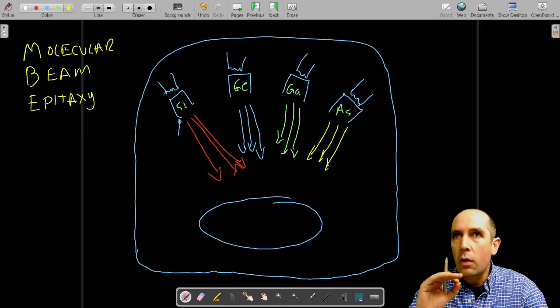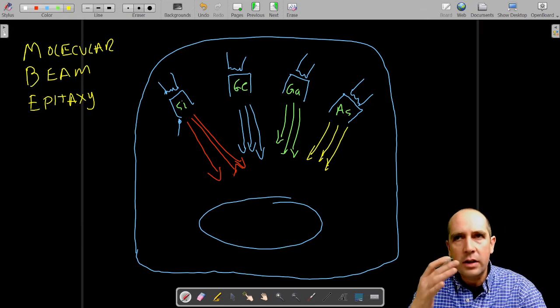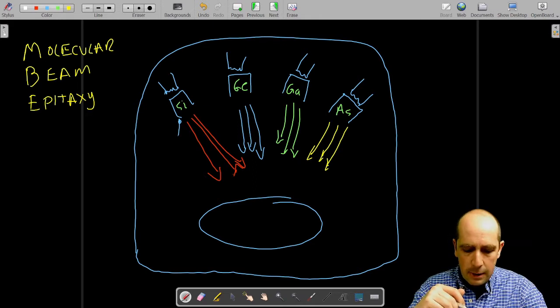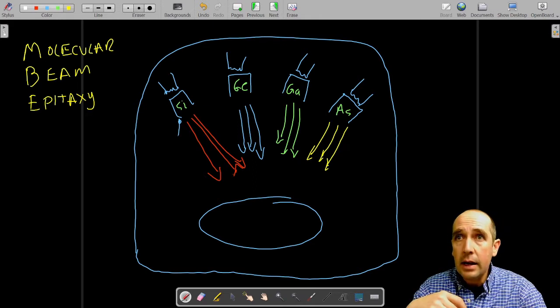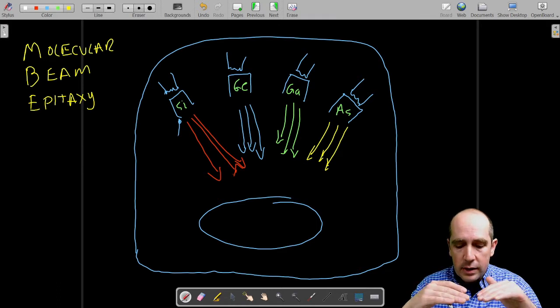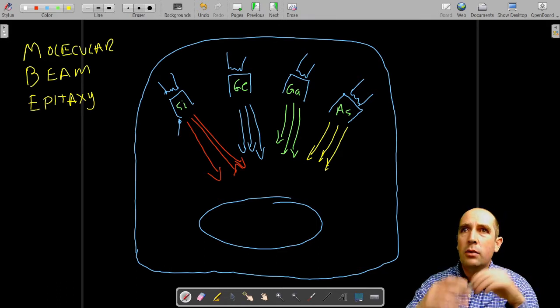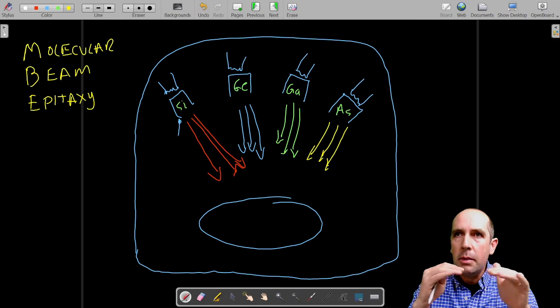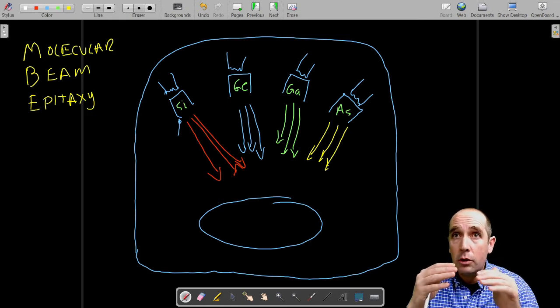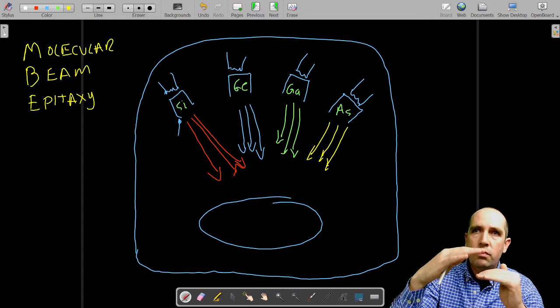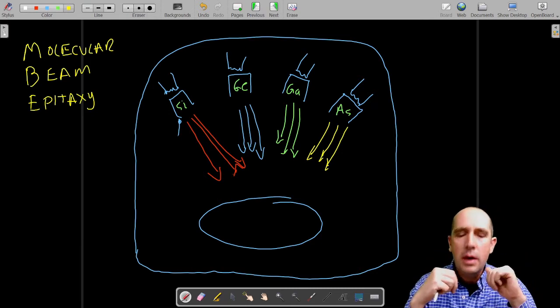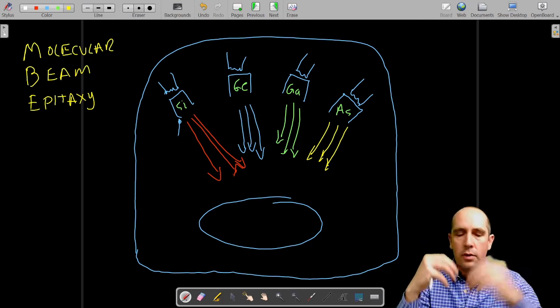The only problem is we can only grow thin layers. So layers are typically below 1 micron. So a few nanometers, or a few tens or hundreds of nanometers, not just a few microns. And the idea is that with these we can start making layers in which we can vary the chemical composition. By chemical composition, I mean, for example, you can use silicon and then put, in principle, let's say, a germanium layer and then back to silicon and so on.